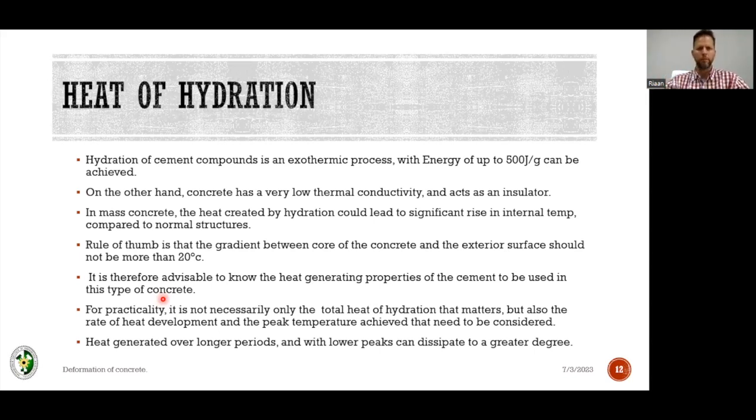But anyway, needless to say, the test cubes taken were tested for a period of about 5 years afterwards, and the strength continued to grow. The temperatures inside the concrete never exceeded 25 degrees centigrade. They installed a temperature probe in the dam at every 4 or 5 layers of roller compacted concrete, as close as possible to the center of the dam, and also on the perimeter, to monitor these temperatures as they climbed and subsided again afterwards, and 25 degrees was never exceeded.